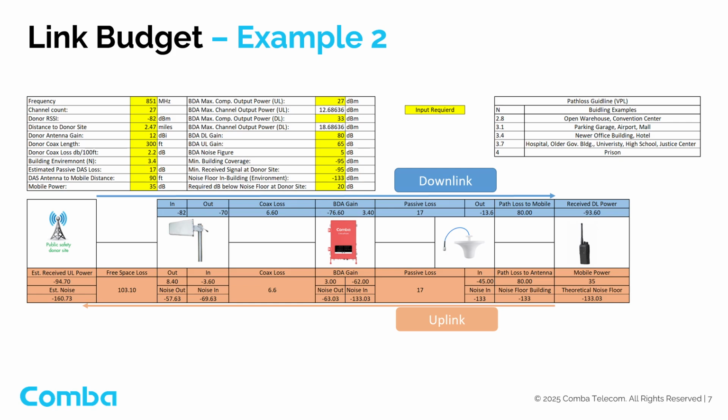It can also be used to validate IBwave or RAN plan design link budgets for accuracy. Additionally, because certain link budget calculations can be complex or unavailable in programs such as IBwave or RAN plan, tools like this offer a convenient way to fine-tune and validate system designs. At this stage, we will not review all the values in this example, as it will be covered later.